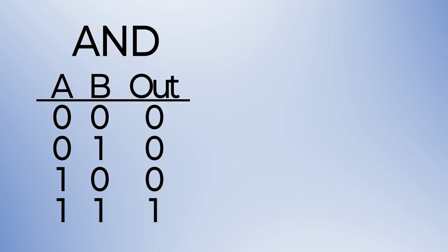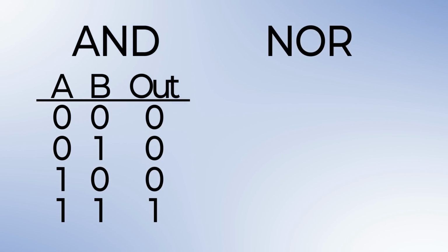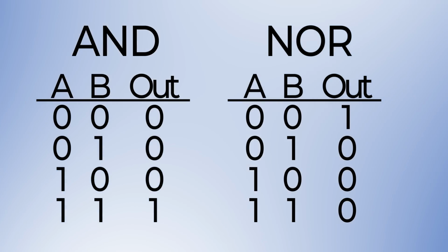Logic gates are a way to do logical operations on whether or not two signals are on and off. For example, an AND logic gate will be positive if both ends of the AND gate are on. Or another example is the NOR gate, the opposite of OR. If one or the other is on, then the result is zero. Using these logic gates together, you're able to create circuits that represent human logic and the foundations of computer programming.